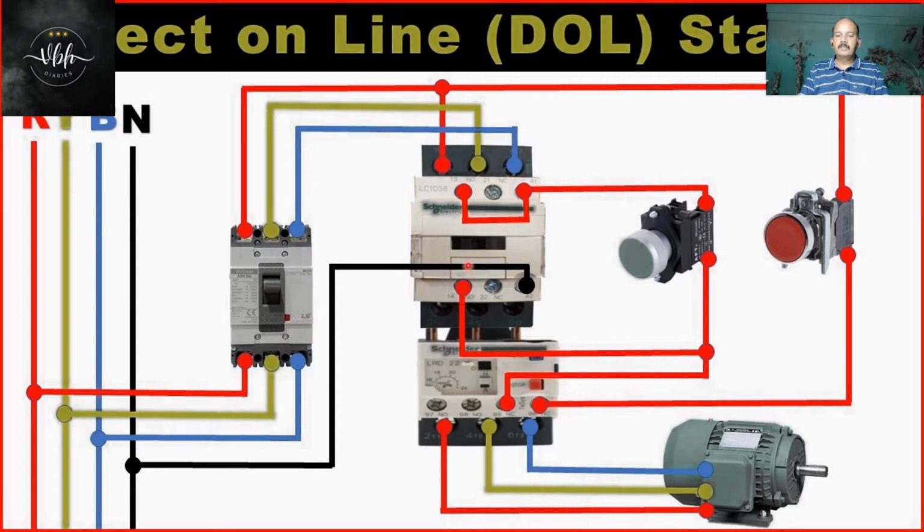Once you connect the overload relay directly to the contactor, a connection is established between them and we need not do anything. The overload relay itself has additional probes which connect to the contactor directly. From the overload relay, it goes directly to the termination point, where we use the terminal block or bus connections for the remote connections, where the field connections can be taken.